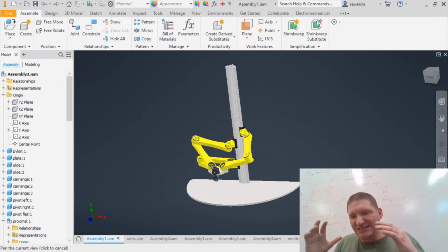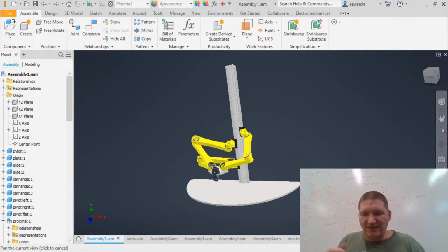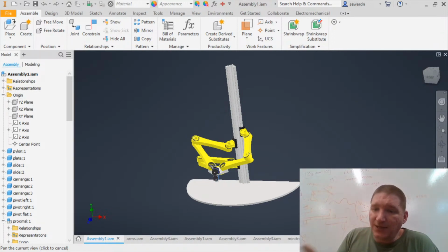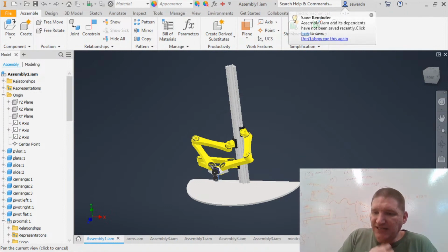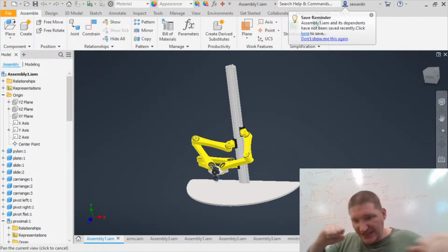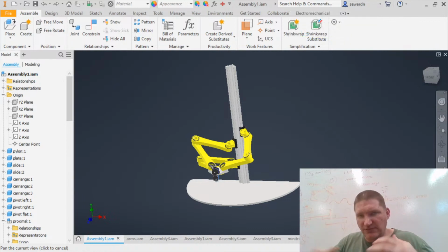It doesn't actually need to know where it is. It just needs to know how to move from there, and everything's consistent throughout. Eventually, whenever I get homing routines, I will use the stall detection. StallGuard is what it's called in the TMC stepper drivers.